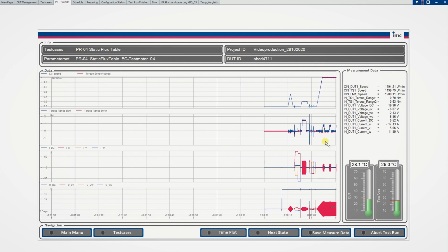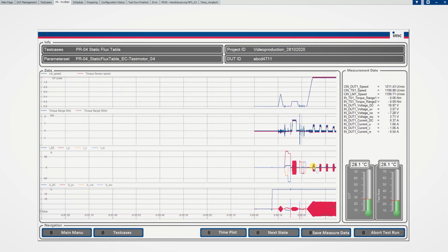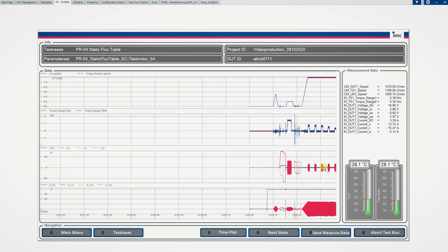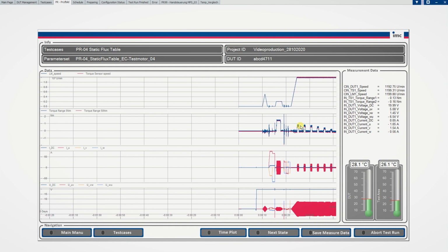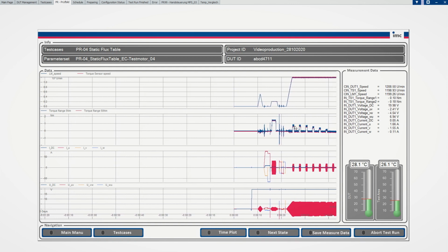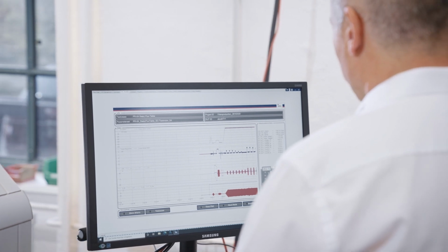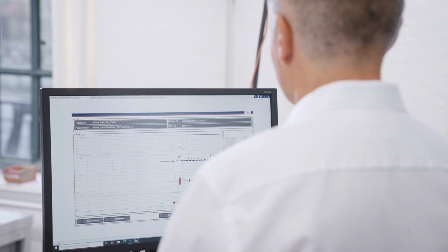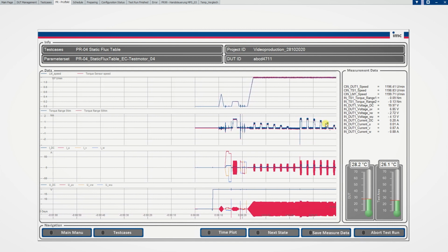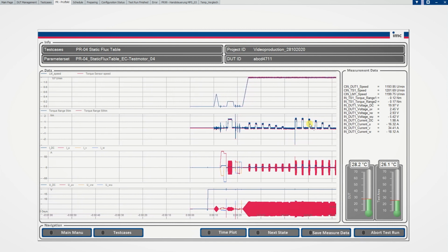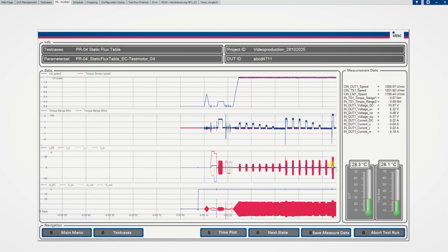We are in line 3, we see the current. This is the first low current range, which goes now over 7 points. And you can see that the torque range is going down while the D current is rising. After these 7 points are done, we go to the next current section, which also goes over 7 points. You see also the torque selection here going down from high to low. And this goes directly to the 3rd section, 4th section and 5th section.